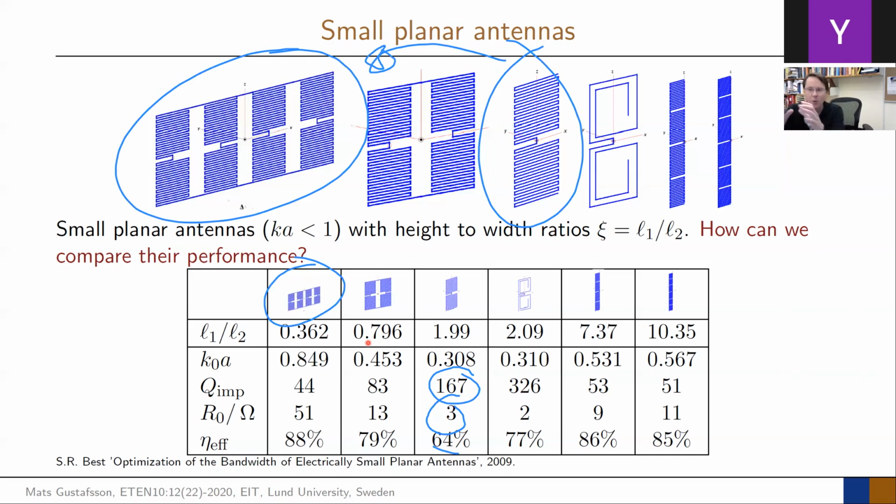So it's a folded type of meander line, which I also showed you before. And the effect of this folding is that suddenly we can start solving these things with, for example, the radiation resistance. So the matching of it is now basically 50 ohm. So that can get out some of these cases.